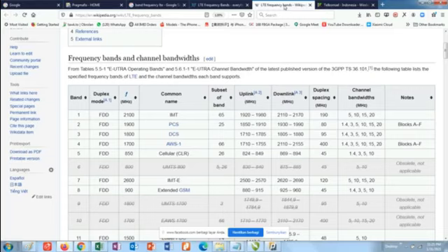Main processor, that is, for example, the graphical processor, we usually call this the VGA chip, or maybe VGA card, which is connected to PCI or PCIe, so it must have its own function. While on the computer, we may not need a baseband because it does not deal with RF cellular, but in the phone there should be AP, GP, BP, DSP, and the last, ISP for the camera.